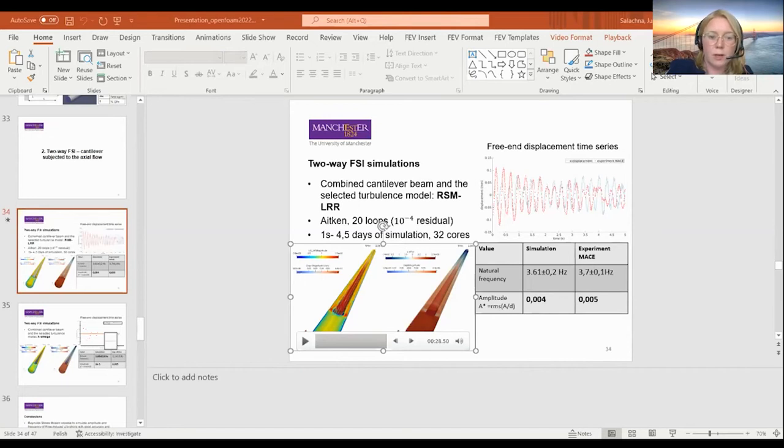Yes, I've used zero gradient on the walls, and that helped. Because previously there was extrapolated pressure as the boundary condition, and indeed there were bugs related to that when restarting. But overall, I had 8 seconds of the simulation, but I don't think that's really necessary to prove that this method is working. It was just for us to see how good we can go. Definitely it is reachable to have 4 or 5 seconds within a single run.